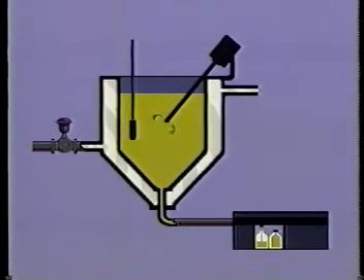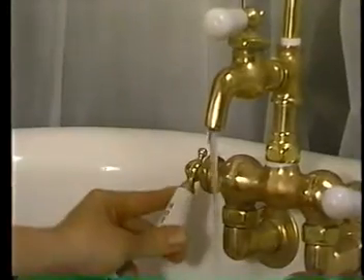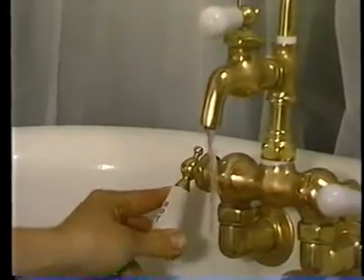The batch process was a large tank of liquid, and when the steam valve was opened, the temperature changed very slowly. As a simple analogy, consider a bathtub full of water. The hot water can be turned on and off, but the temperature of the water in the tub changes only slightly. The bather is quite comfortable in spite of the on-off control action.